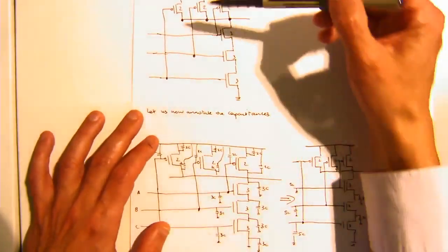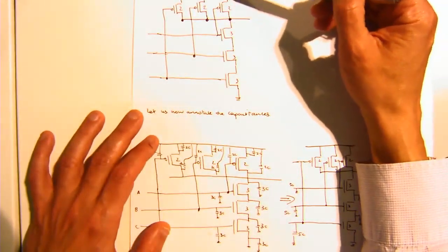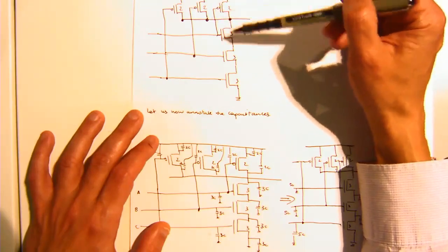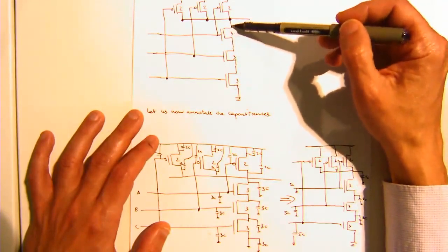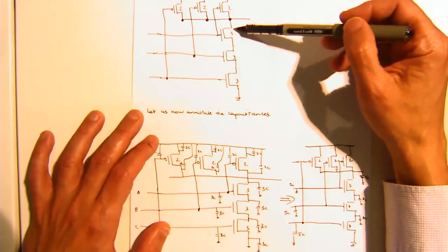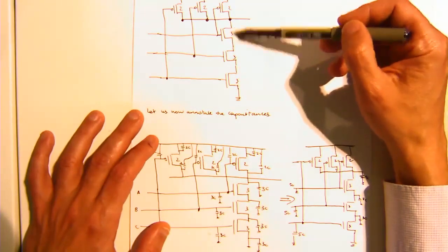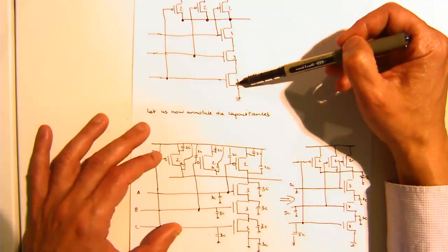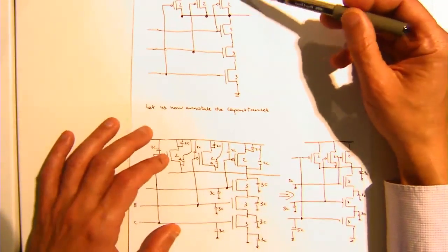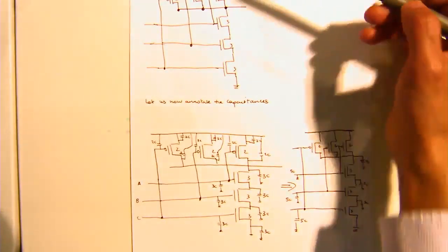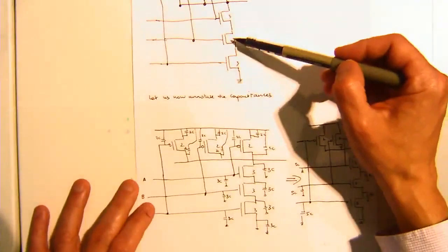The reason is, at any one time, you're driving through one of these PMOS devices, and always you're driving through these 3 NMOS devices. So I'm doing this so that I can minimize the resistance through this. This is usually one of the ways that you design these 3-input NANDs, or even if you did a 2-input NAND, you'd go 2 and 2.